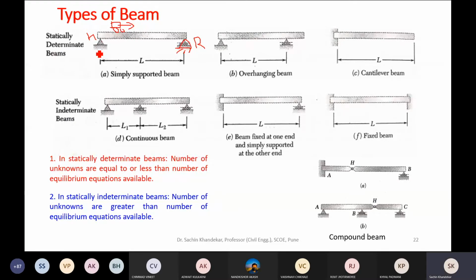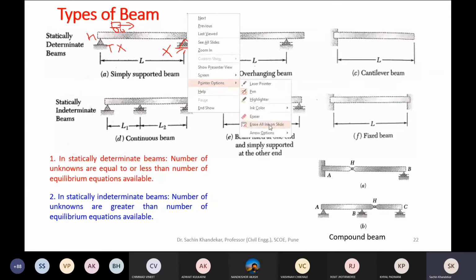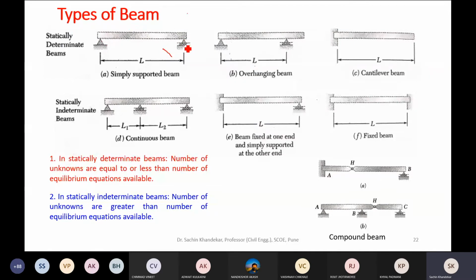Brakes have been applied and both the supports are not allowing translation, and because of that some additional stresses are induced in the supports. Whereas on the other hand, if one end is a roller one and the other end is a hinge one, and we apply the brakes, a horizontal force will be induced onto this beam. Because of which, as this end B is free to roll, additional stresses will not be induced.